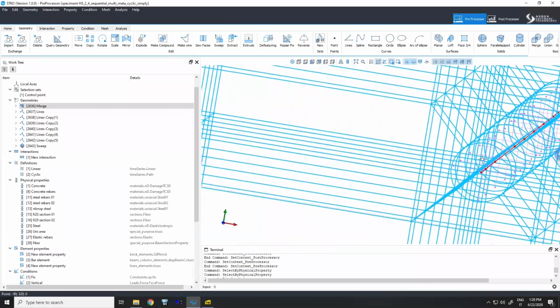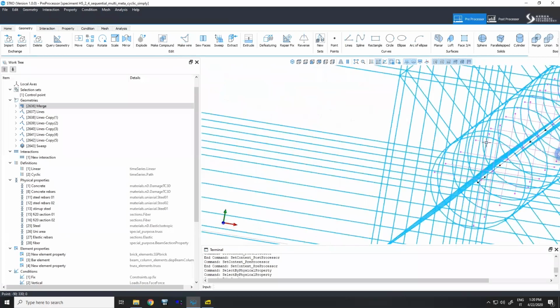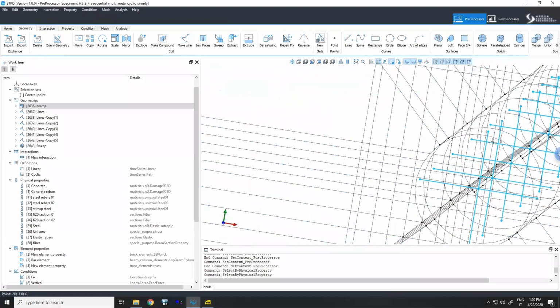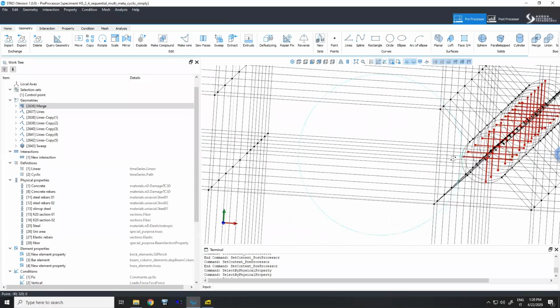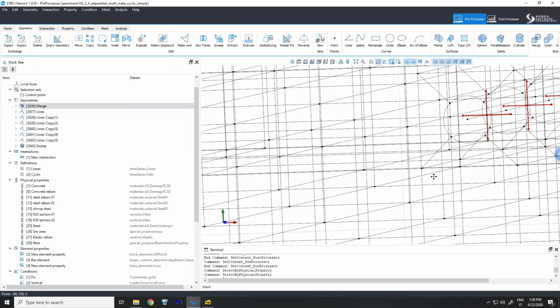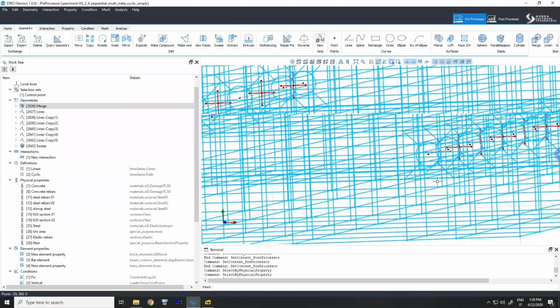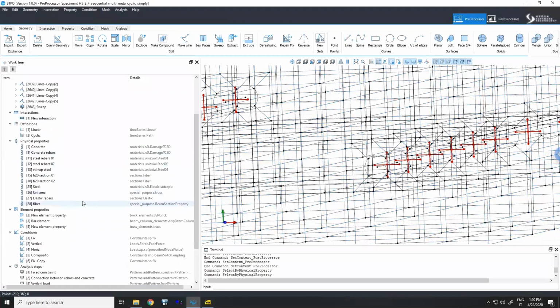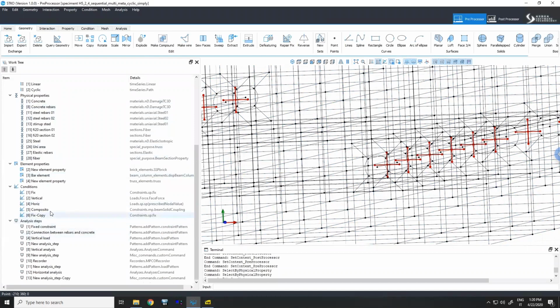And then we created this kind of interaction here, which connects, let me pick it, okay? This one, that as you can see, connects each point of the beam to the surrounding point of the solid. And this one has a special boundary condition, which is called beam to solid coupling. It basically is a kinematic condition that couples the master node of the beam that has displacement and rotations to the slave node of the solid in such a way that the node of the solid will displace according to displacement and rotation of the master node of the beam.